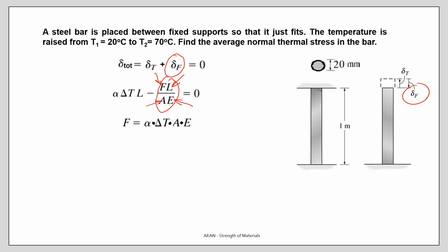So what do I know and what am I looking for? Everything is known. All I need to find is F. F equals alpha, the linear expansion coefficient, times temperature change, cross section, and the modulus of elasticity.